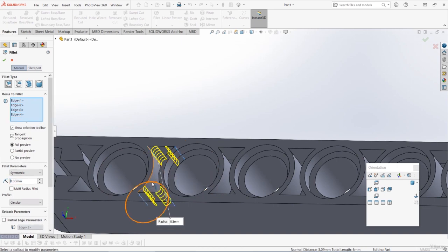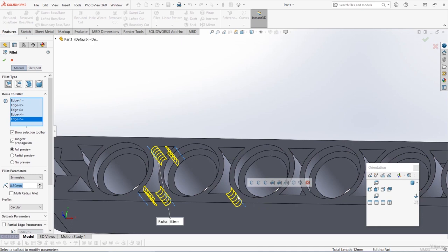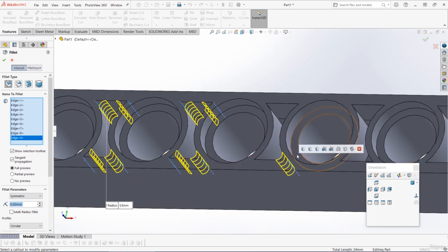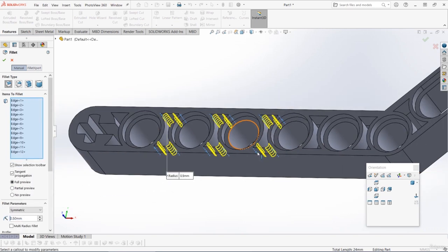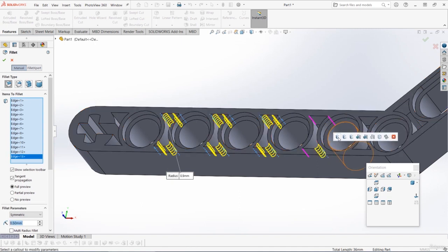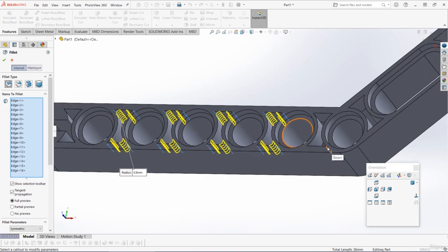You can select them manually. You should also find that when you select one, you get this edge selection toolbar pop up. This will give you different options to select multiple edges at the same time. So I'll show you again with this cavity. When you select the first edge, we get this pop-up toolbar, and then if we just hover over, for me, it's that first option that will allow me to select all 4 edges within that cavity. That just saves a little bit of time.